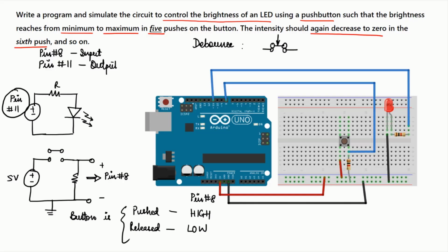So it is important that whenever we are pressing a button, we consider some sort of buffer time. After that short buffer time, we again note the value. If it is still on, we consider that yes, this is on. So you pressed a button and you consider some buffer delay of say 5 seconds, and after 5 seconds the button is still closed, so you say yes, the button is closed. This kind of a debounce mechanism needs to be brought in whenever we are dealing with a physical switch.